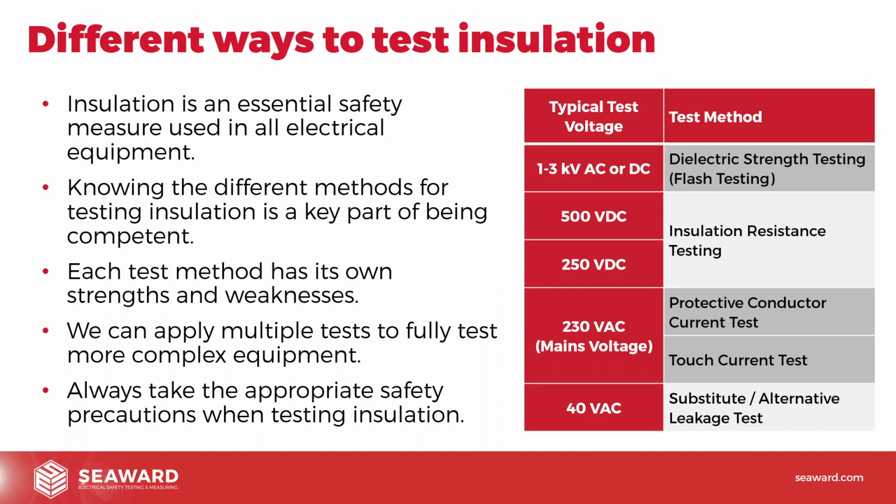Going down to the next step, we talked last week about the insulation resistance test, and the options to do a 500 volt test, or if we've got sensitive or surge protected equipment, we might do that at 250 volts. Now, the insulation resistance test is pretty much the standard PAT test that we would carry out. And the 500 volt test does put equipment under stress. There is the possibility, as we discussed last week, of potentially damaging sensitive equipment by doing the 500 volt test. But of course, we're talking about a voltage that's more than twice the supply voltage. So again, it's giving that equipment a certain amount of stress to find those faults and give it the opportunity to fail under test conditions rather than fail in real life. But we've got those two options there for insulation resistance, 500 volts or 250 volts.